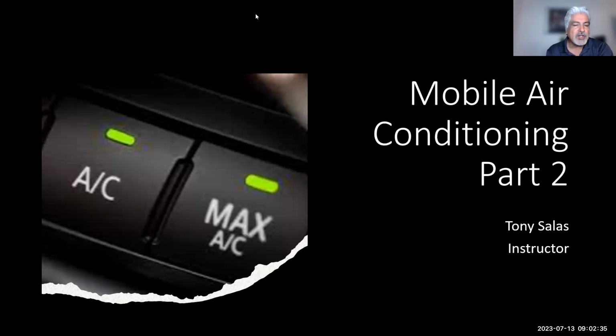We introduced air conditioning. We said that air conditioning cleans, cools, and dries the air. We saw that the AC system has a pressure temperature relationship with the refrigerants. And we saw that the 134A along with the 1234YF have similar pressure temperature relationships, so they're not too much varied.